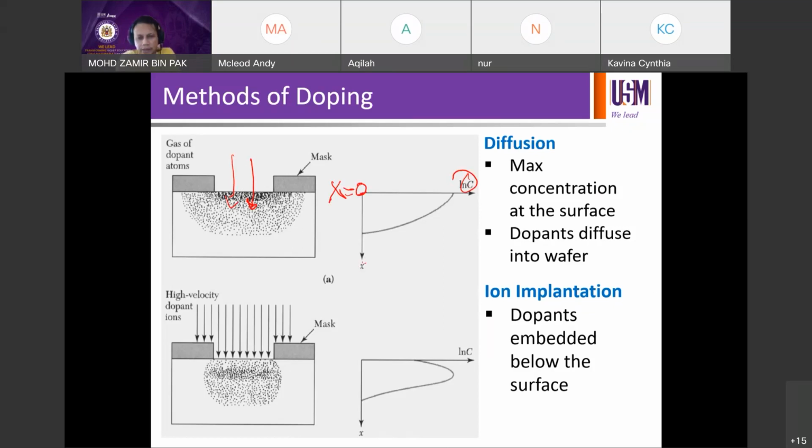We flip the axis, and you can see that it takes that kind of profile for this kind of junction. Say this is p-type and your dopants are n-type, then you will have your peak concentration at the surface. Normally we call this N0. Then as you go into the depth of silicon, you have a function N(x) equals blah blah. But the surface concentration is called N0.